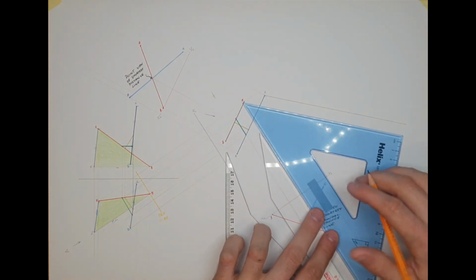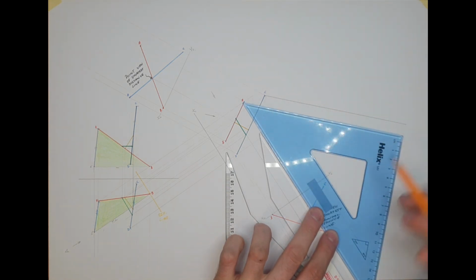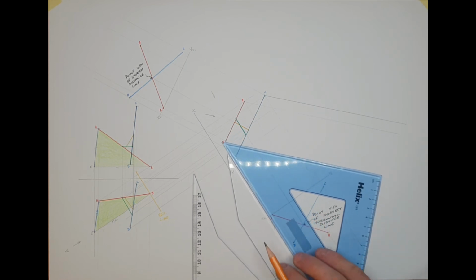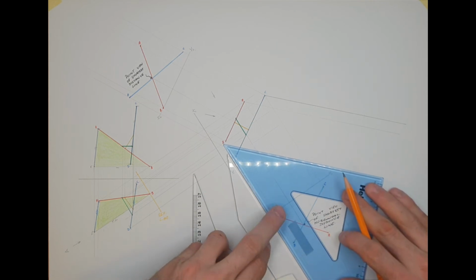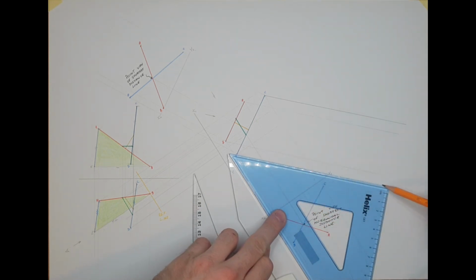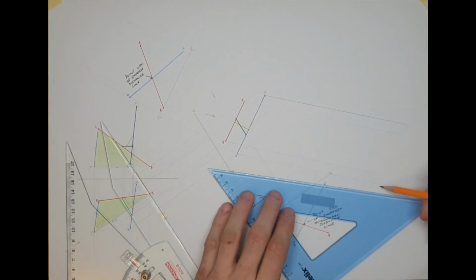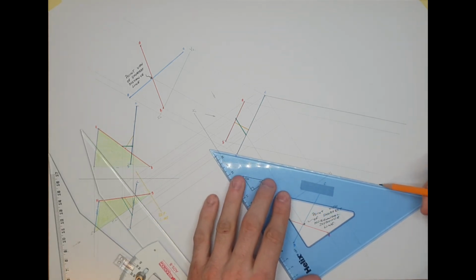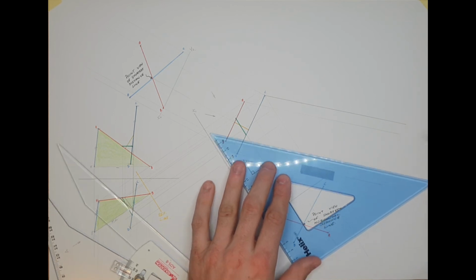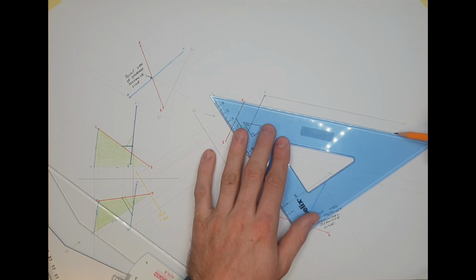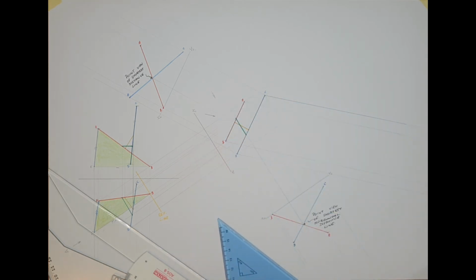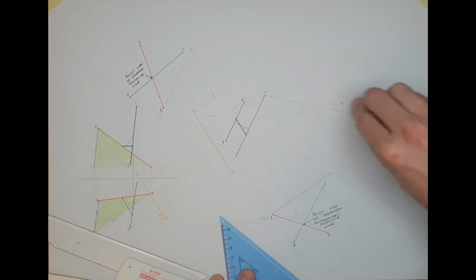I've taken point C, I'll now take point A. I went really heavy on that first one, I really shouldn't have done that. I'll move off my T-square for a minute and I'll hold the set square and do sliding here. And I'll take those two points as well. I probably need to extend them on a little bit further. I'm going to try and keep these views from overlapping if at all possible. So I'll just extend them out as far as they need to go, or as far as I can go. And there we go. I'll lighten this line. I drew that way too heavy there.